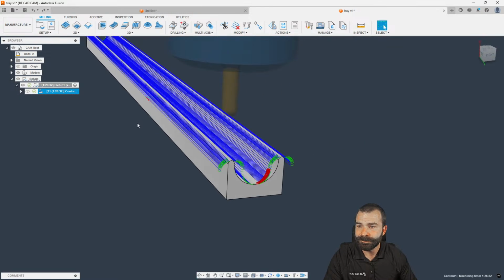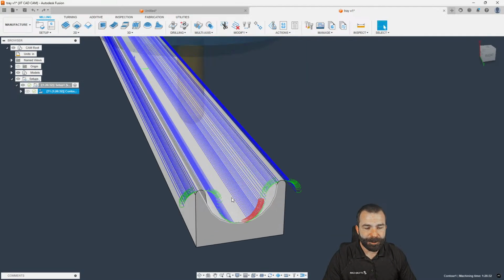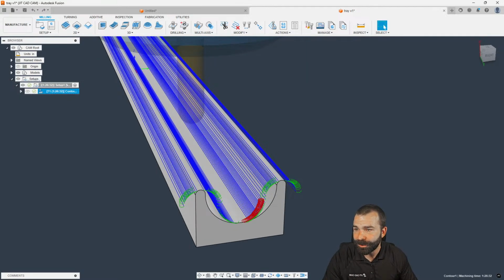Better through, got a question there, maybe a solution that came in. I have actually gotten a better finish through the dip than running the ball mill along through the dip. Okay, so you go across the part versus along the part, if I'm understanding that. When the ball mill is climbing near the bottom, it starts to cut. Yep, so completely agree. And we could look at another way to do that on this part in particular. And Mr. Powell, you've got to remind me, do you have the machining extension?